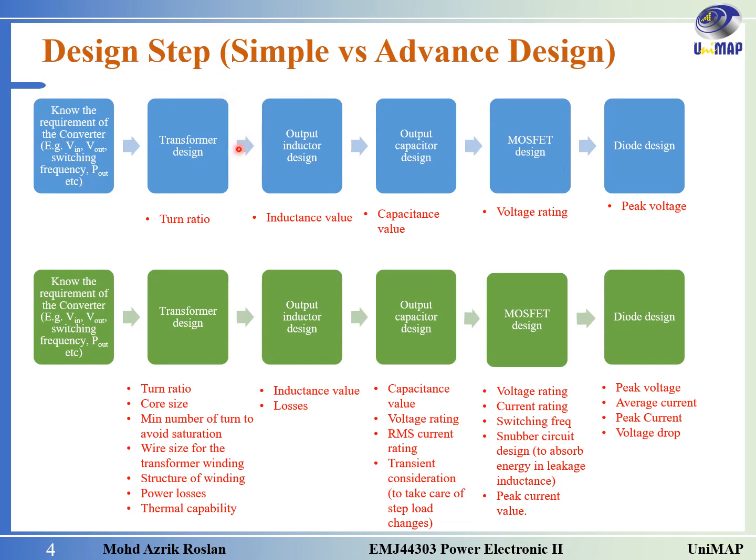For the simple design step, which we will use for this course, for the transformer design, we just need to calculate the turn ratio. For the output inductor design, the inductance value. The capacitor design, we need to find the capacitance value. For MOSFET design, we need to calculate the voltage rating. And finally, for the diode design, we have to calculate the peak voltage.